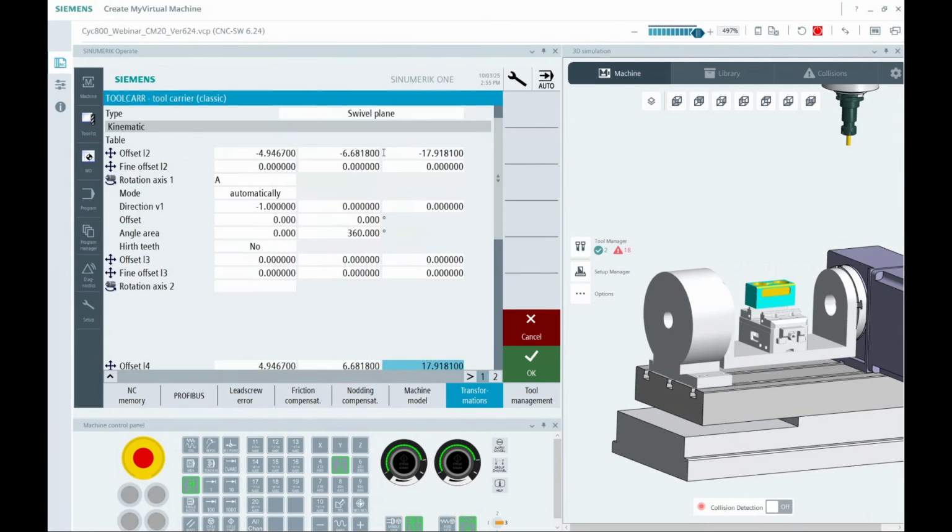So that's pretty standard. But if I found that I had a discrepancy in my center line, these two numbers would be my two culprits. And then whatever I change them to here, negative, I just got to put the inverse down here. The X component means nothing, because if you think of the X as the center line of the A, which is infinite, right? I have an infinitely long center line. It doesn't stop anywhere. The X could be significant had I maybe had a secondary rotary, but I don't in this scenario. So you could leave this X at 0. I could put 1,000,000 here. It doesn't matter. But if I do have a number here, it's not a bad habit to at least close itself. But this is what sets up the transformation.